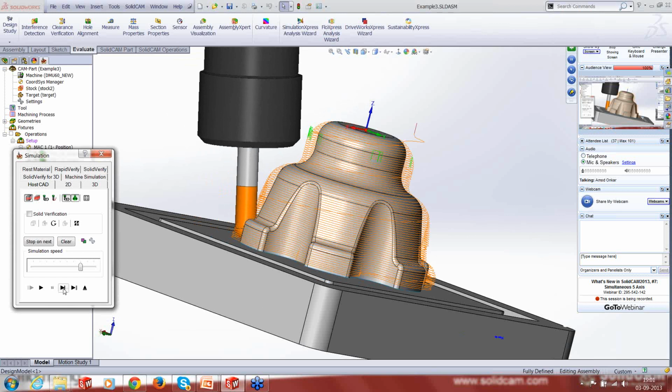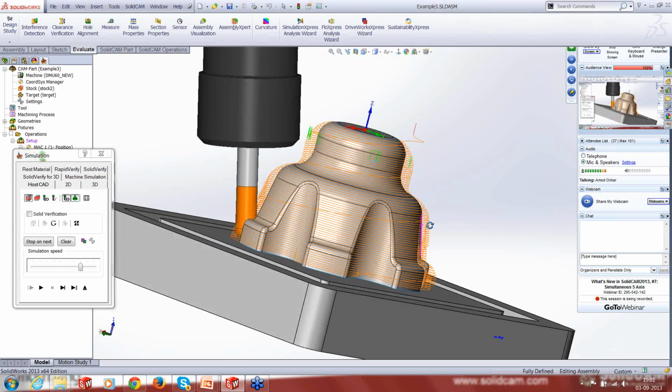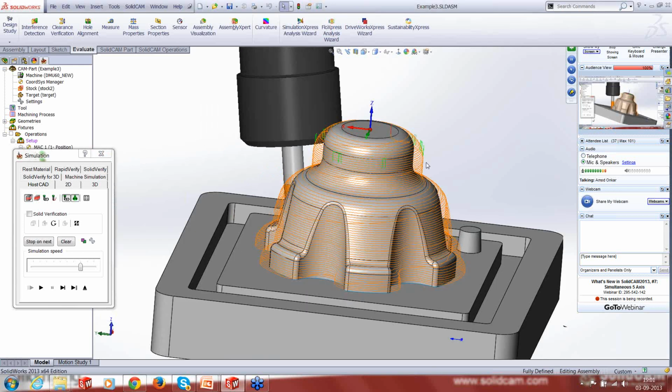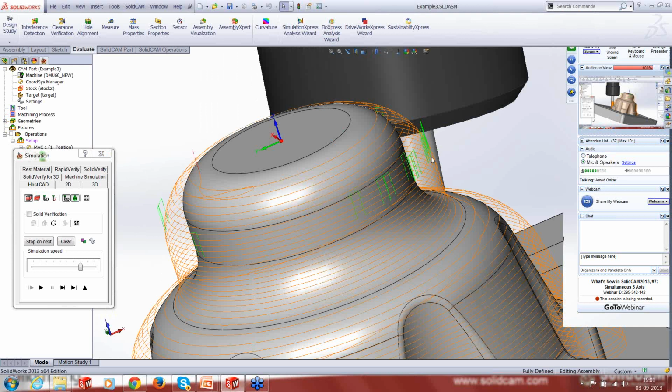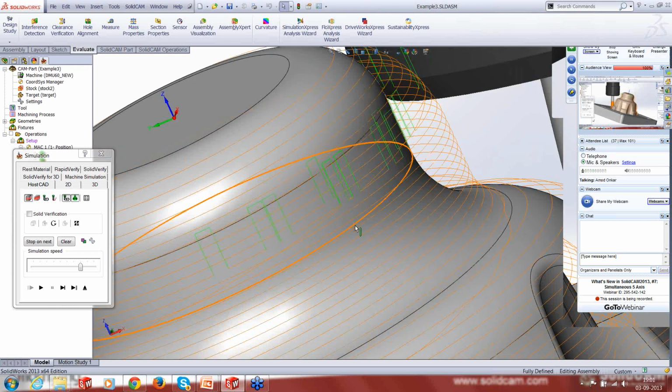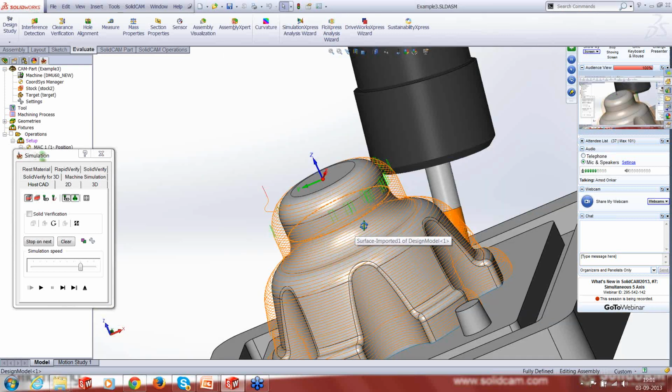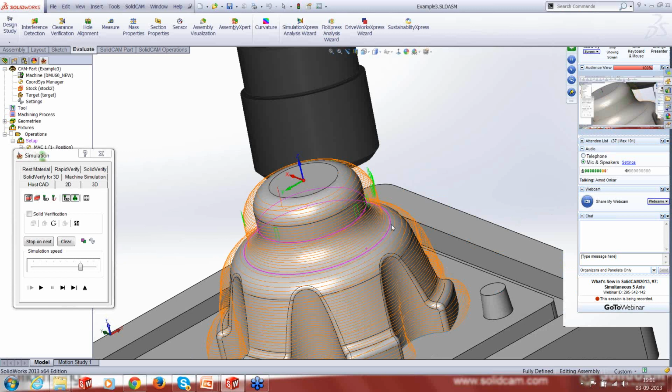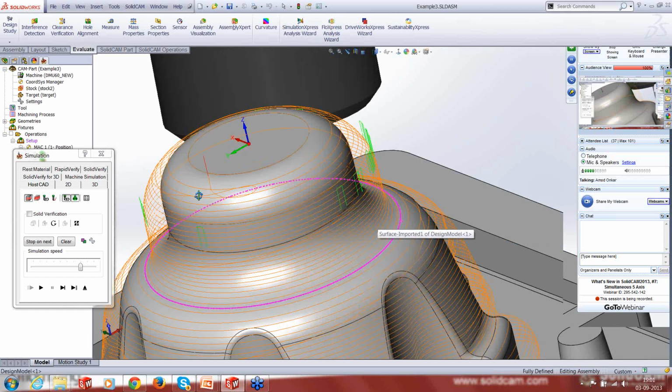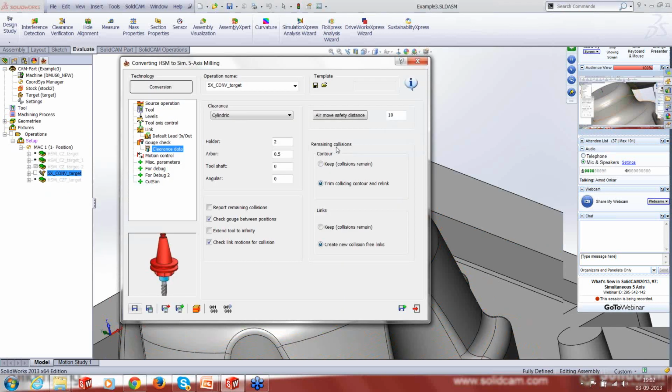Okay, this is exactly happening the way I want it to happen, but what are the other things that are happening which I don't want? These jumps. Can you see these jumps? The toolpath has got trimmed itself, it has jumped up. It's probably finding very, very fine collisions between the tool and the part. And that is the reason it's gone to this particular area out here, and it says if there are collisions along the contour of cutting, trim those colliding contours and relink. This is what it did.